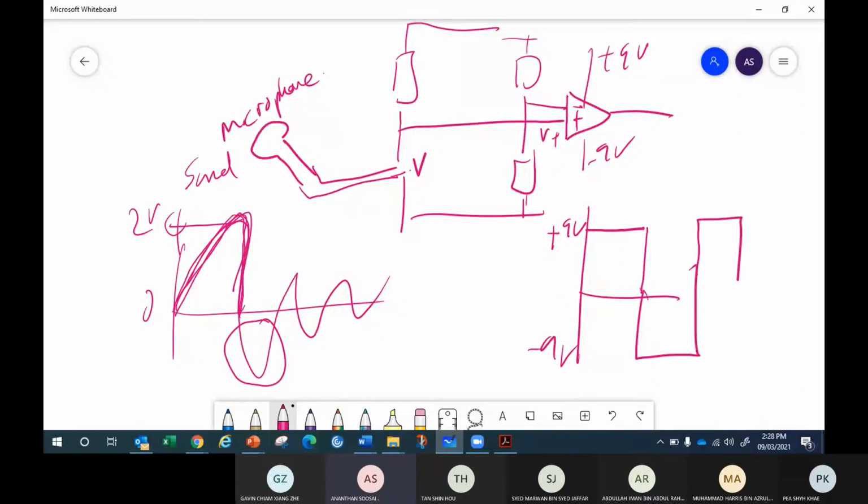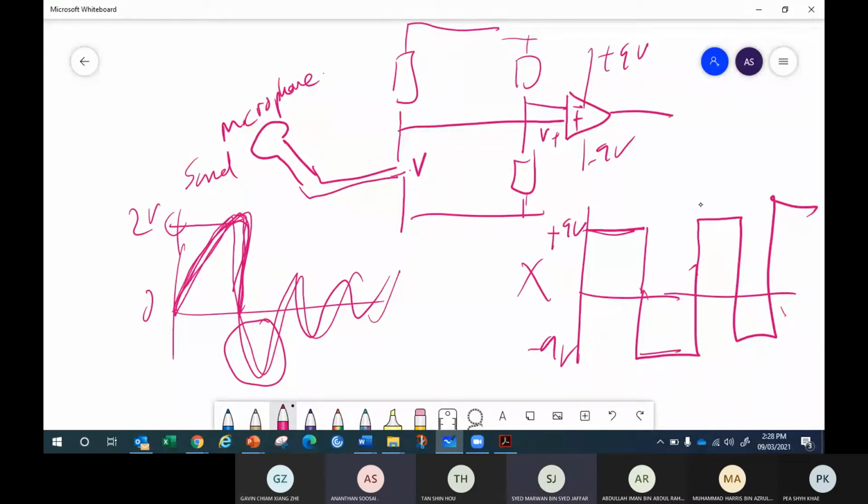So what is the op amp going to do? It is going to saturate all the input. No value in between. Just either positive 9 or negative 9. So the opera singer, whose singing has a pattern, this pattern cannot be retained. It's going to be saturated. Is this good or bad for the music? This is not good, right? If you want to amplify a sound, you need to retain the pattern, right?